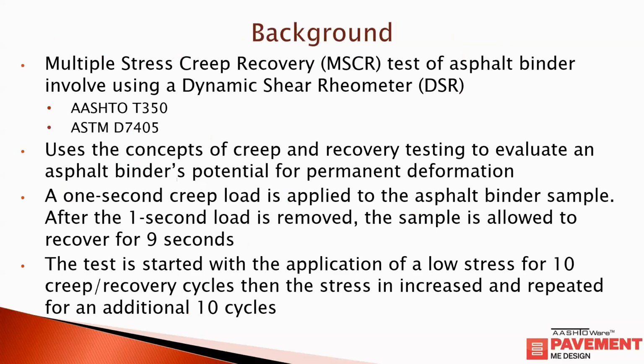Yeah, so let's start with the background. The multiple stress creep and recovery testing, the MSCR test of asphalt binder, involves using a dynamic shear rheometer, the DSR. There are two standards for this test. The first one is AASHTO T350, and the other one is the ASTM standard, ASTM D7405. This MSCR test uses the concept of creep and recovery testing to evaluate how asphalt binder can stand against its potential for permanent deformation.